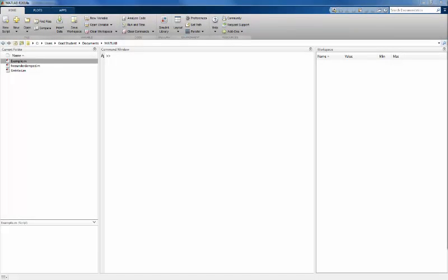The next command you will encounter is ginput. This allows you to pick points off of a plot which you can assign to a variable. Now this can be very useful because it allows you to have the x and y values available to use in your program. But before we do that, we need to make a quick and simple example script file to produce a plot. And it just so happens that I have one right here.